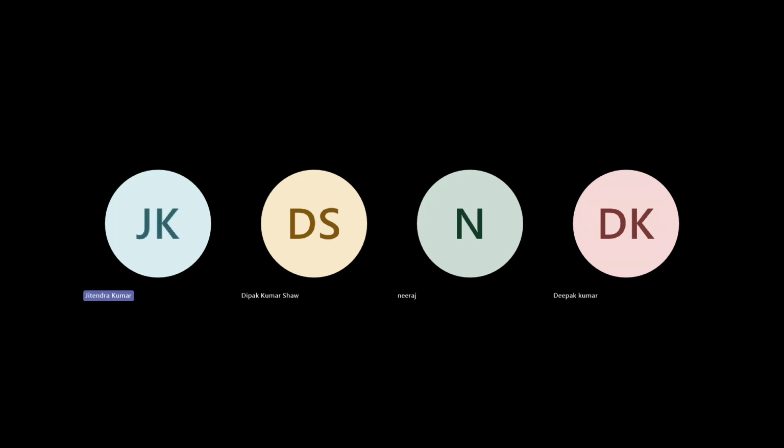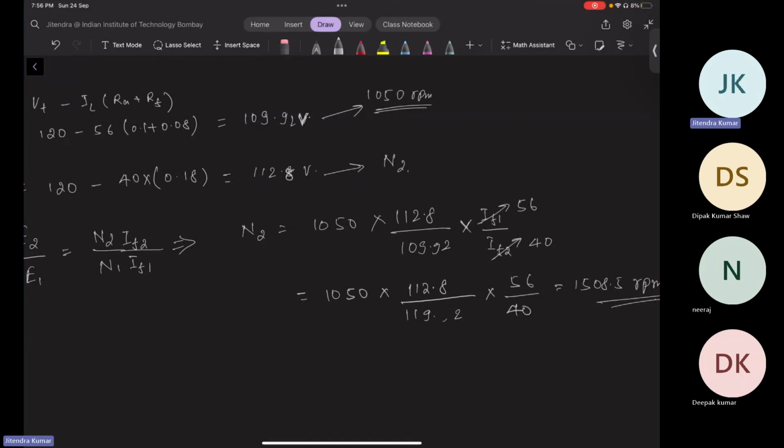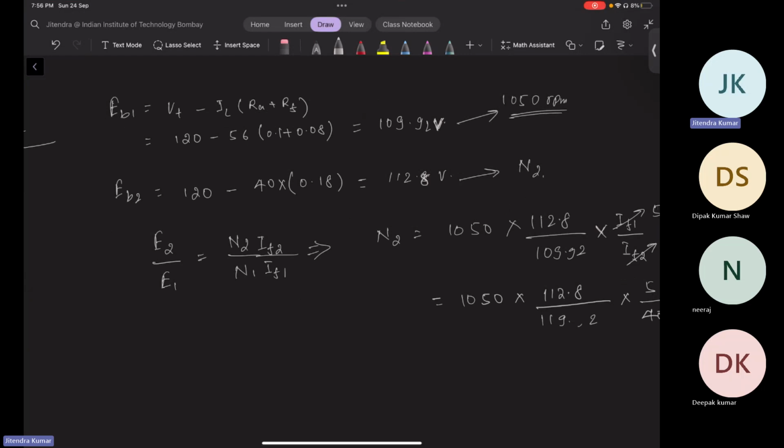It might have two speeds, one corresponding to a below base speed, other corresponding to the above base speed. Why below base speed I am saying, because this is a machine, and here below base speed, if you are reducing the flux indirectly by reducing the line current, you are reducing the torque of the machine below base speed. But at above base speed, you are again doing the same thing, right? You are reducing the field current to operate it into the field weakening mode.